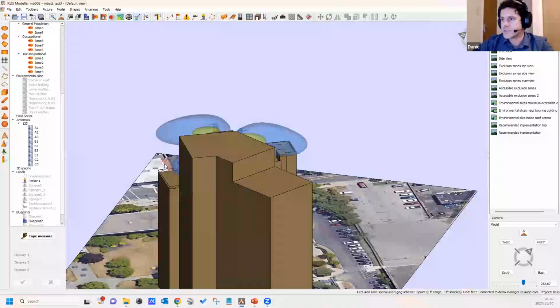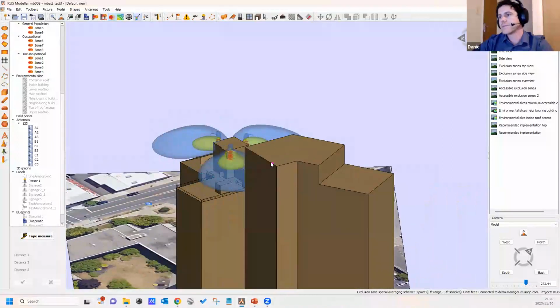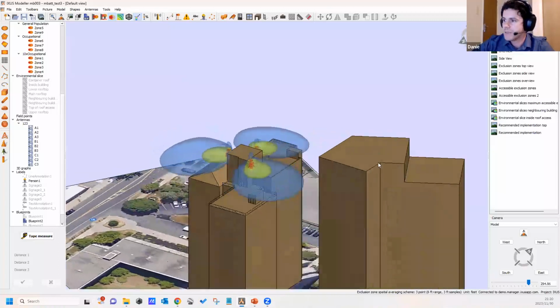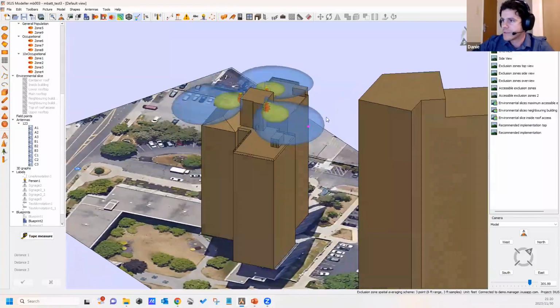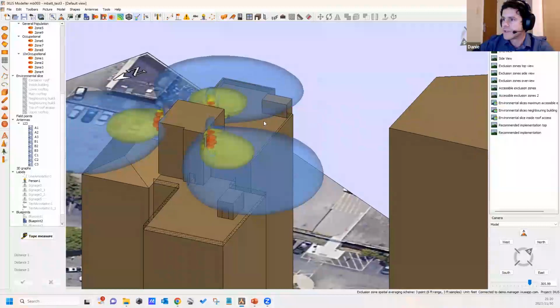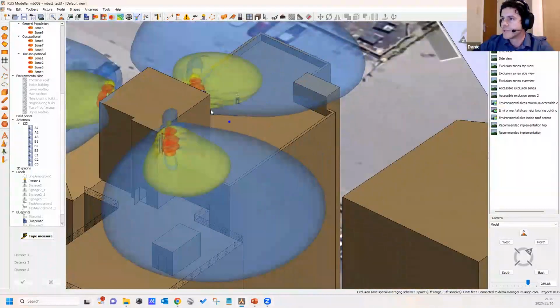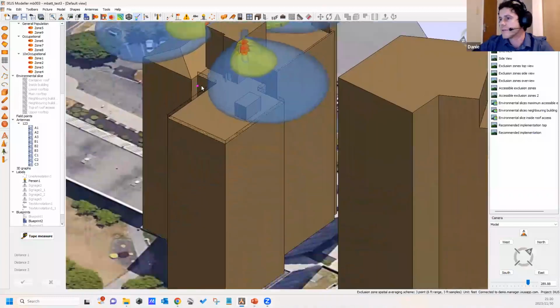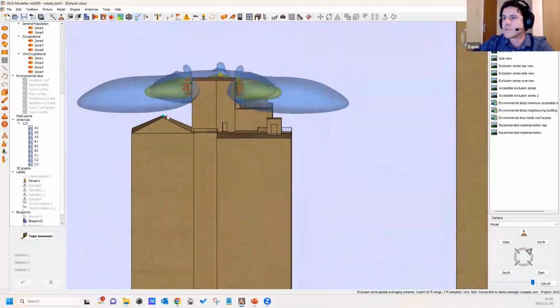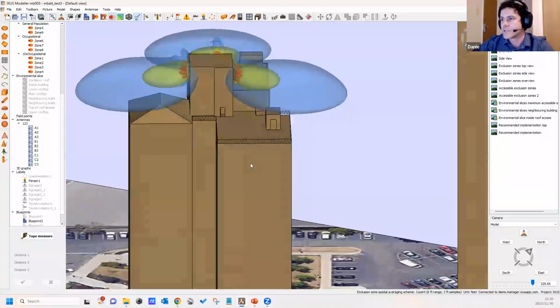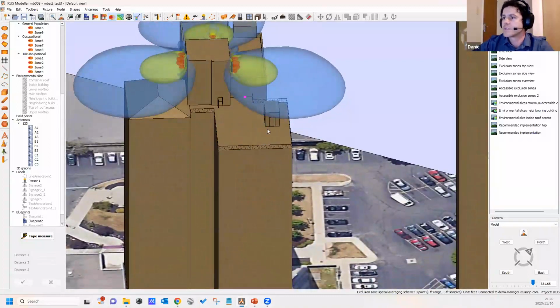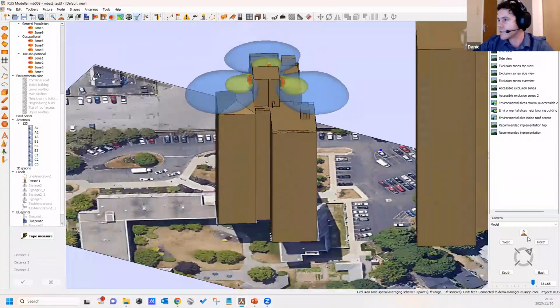And as I mentioned, this is using the FCC OET 65 with a 6-foot spatial averaging scheme. By looking at this, we can establish that this area over here is definitely going to be an area that we want to assess very closely. And we would want to know exactly the height of this structure over here, and maybe this. These are going to be important things to establish.